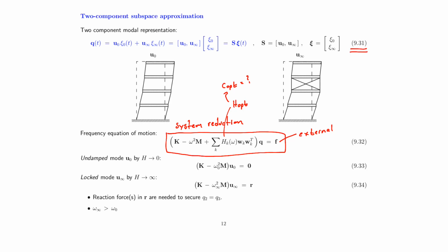The classic case is that we say, alright, we would like to design our damper to a particular vibration form. That could, for instance, be this vibration shape here, the first vibration mode for such a building structure. So we're looking at mode number 1. Could be any mode, but the illustration here is certainly for the first vibration mode.